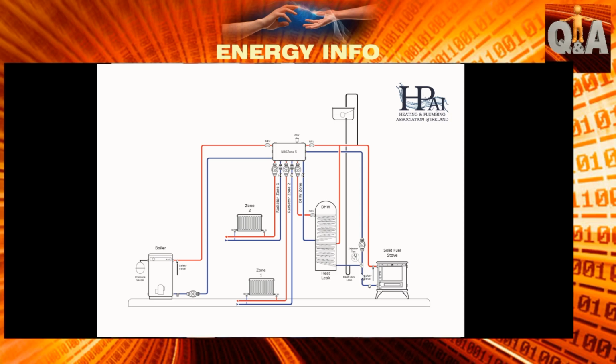When it's just coming up towards that temperature, turn the stat backwards from 90. Obviously it's wired, so it makes a circuit when the temperature is rising, and when it's just less than what you can actually hold for a second, you bring the stat back where it clicks. If it happens to be 55 degrees, leave it there, but I'd rather go by that method rather than going by a number on the stat, because the stat might be out of calibration.